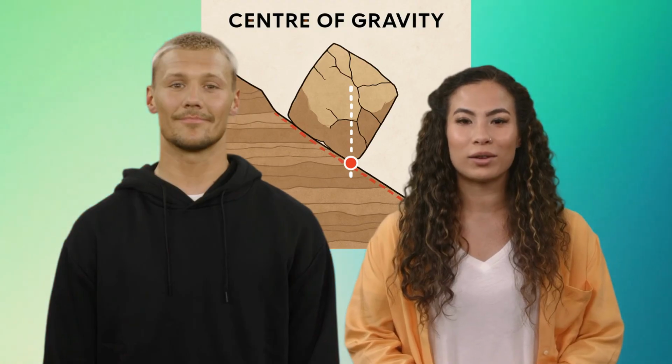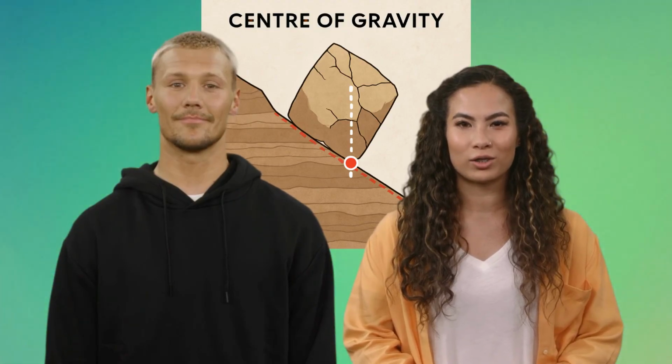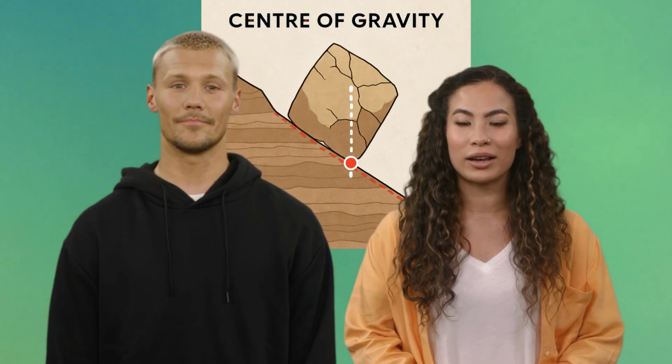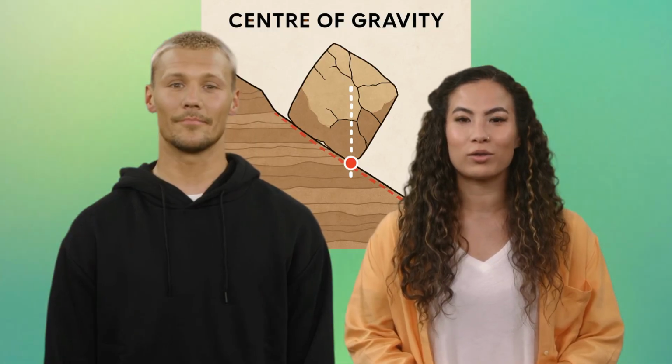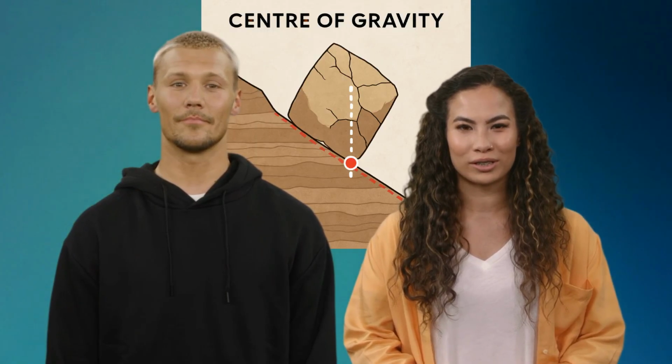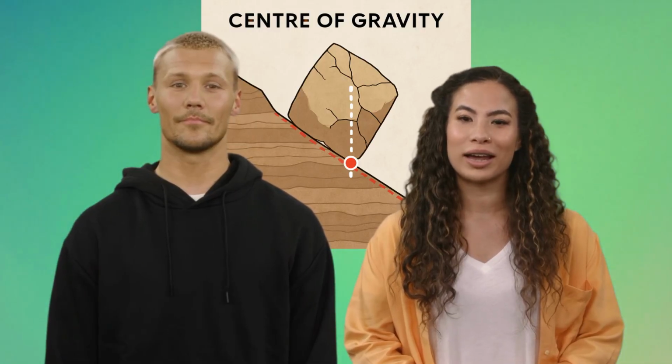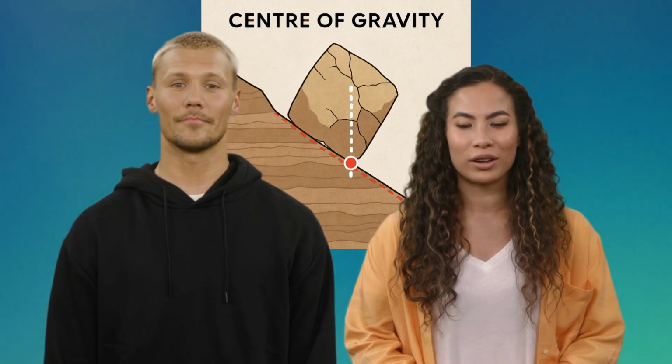In today's video, we're going to focus on the concept of center of gravity and how it applies to assessing hazards in a mining work area. Understanding where the center of gravity lies, whether it's within a slope, a rock block, or a wall, is critical to recognizing how and why instability can develop.